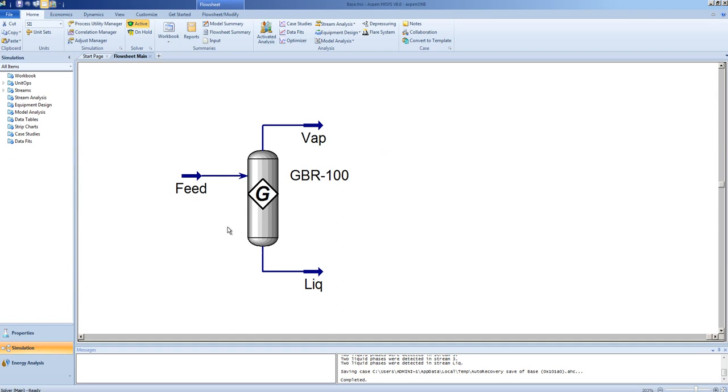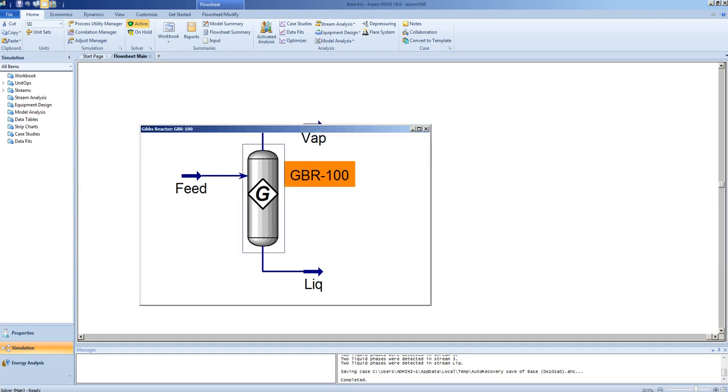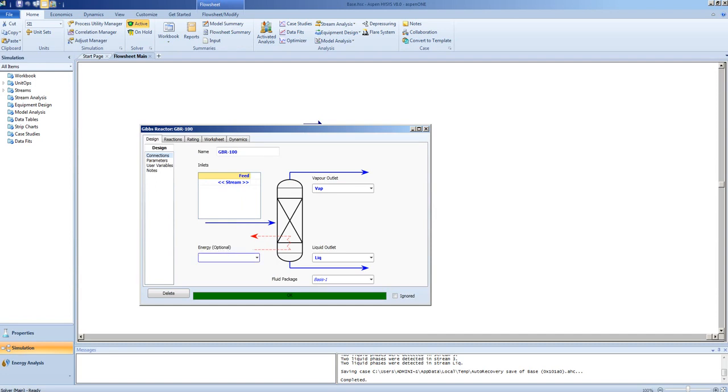And this is an adiabatic reactor. There is no exchange of energy with the surroundings. In fact, we can add an energy stream, R-Q. Note, because we have added a variable, our degrees of freedom is now +1.